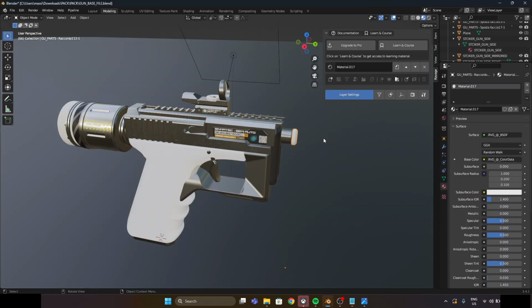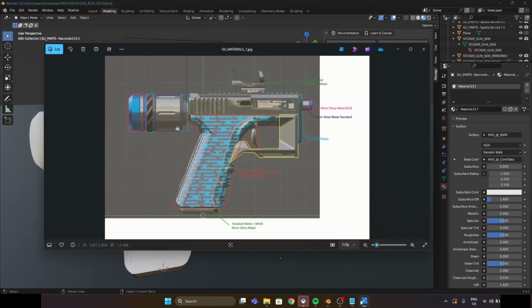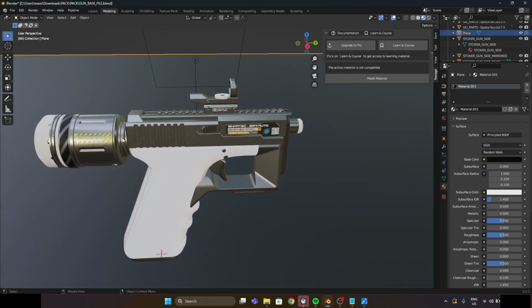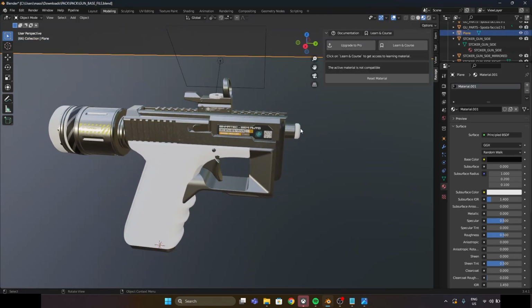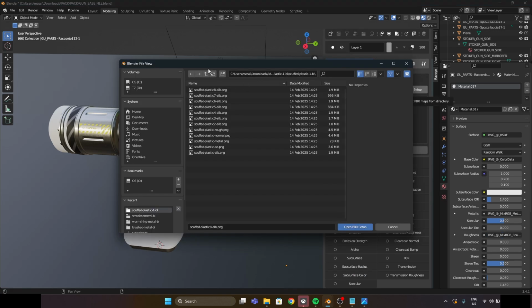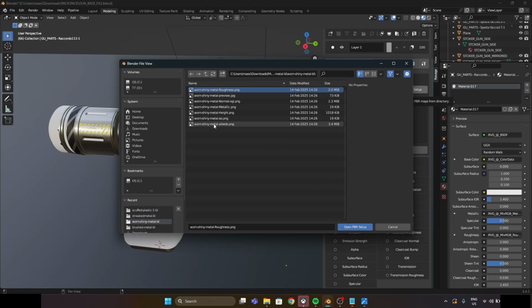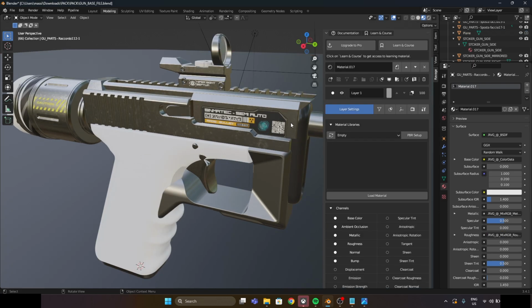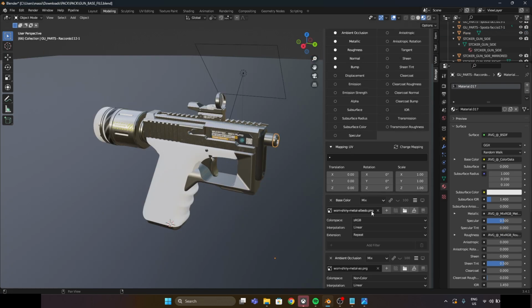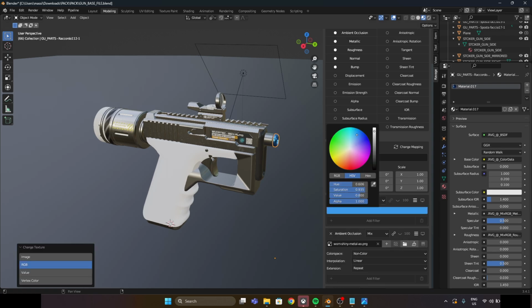So now we need to apply the material for this part that is blue. So this kind of blue here. And I need to adjust the material a bit. So I would just go inside the material, create a new layer, PBR setup, Worn Shiny Metal. Now you can see it's just this color. You just go inside the material and it's in the base color. We just remove the image. Clicking here, we go to just the RGB value, and choose a color we like.